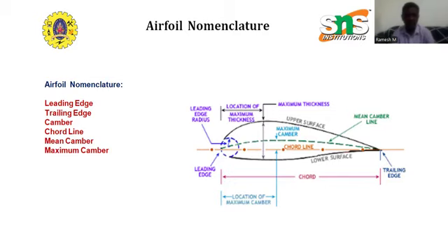The leading edge marks the frontmost point of the airfoil, where it first encounters the oncoming airflow. The shape of the leading edge is a crucial factor and it is tailored to suit the airfoil's intended function. For high-speed airfoils, as found on modern fighter aircraft, the leading edge is razor sharp. It is designed to efficiently slice through the air. In contrast, airfoils intended for greater lift at lower speeds, such as those on certain small engine aircraft, sport thicker and more substantial leading edges.